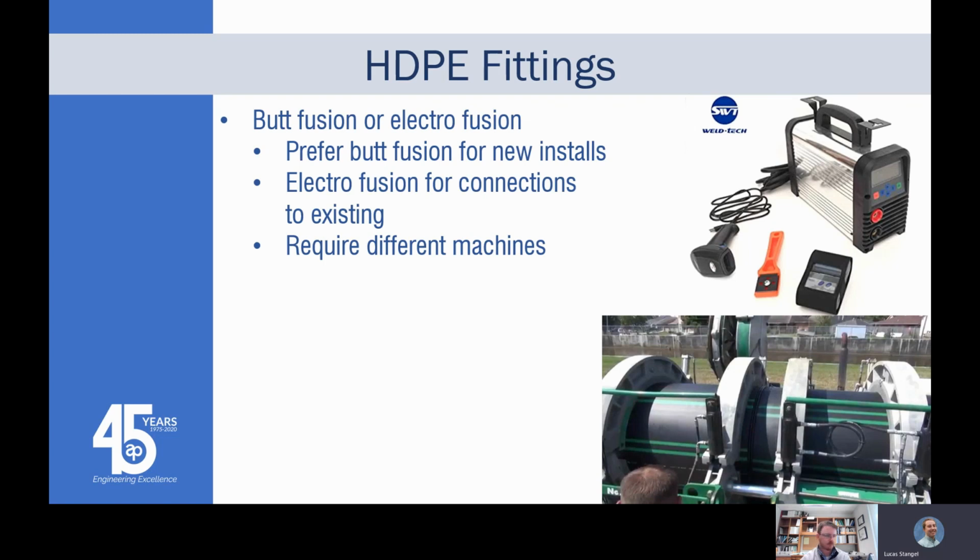So yeah, they're kind of like we talked about. There's the butt fusion. That's that machine on that lower picture. There's a hot plate, where you stick the pipes in there. It trues up the ends, has a hot plate to warm up the two ends, and then presses them together. That's the preference for fittings, joints, everything, as it provides the best joint.